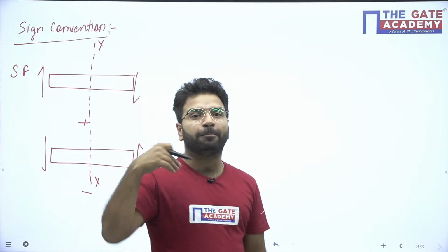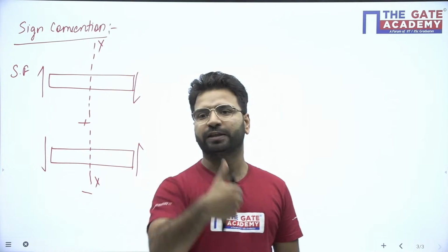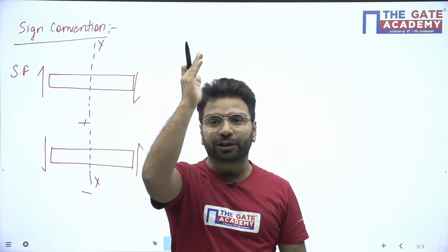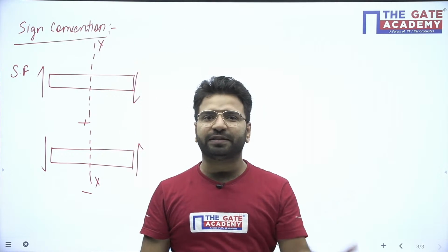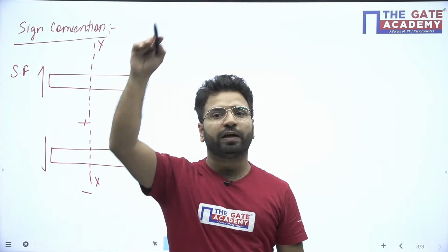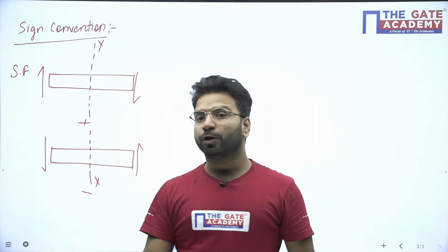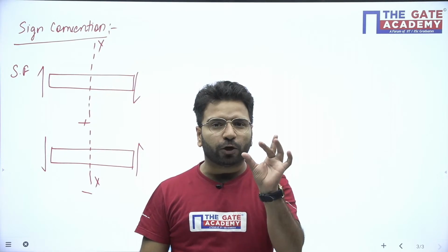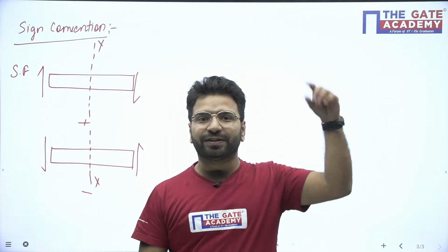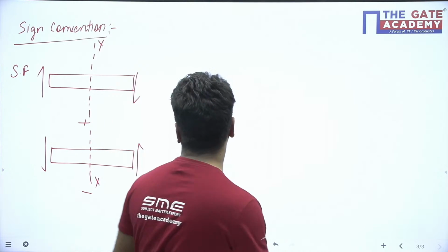Sometimes we confuse the force or reaction sign convention with the shear force sign convention. We always assume that upward is positive, downward is negative. Generally we consider this sign convention like our coordinate axes, plus y upward, minus y downward. So we get confused sometimes. Don't mix the sign convention of shear force with the reactions. Reaction sign convention is completely different, shear force sign convention is completely different. So don't be confused with that.